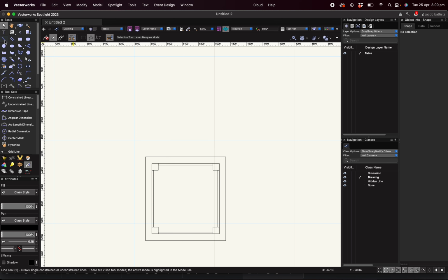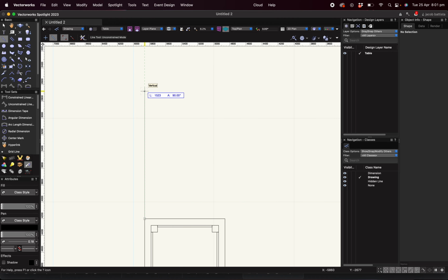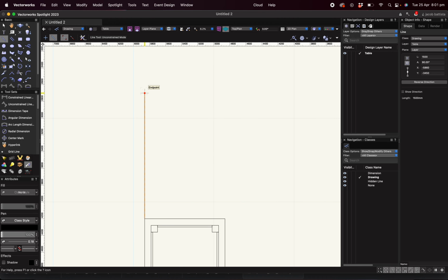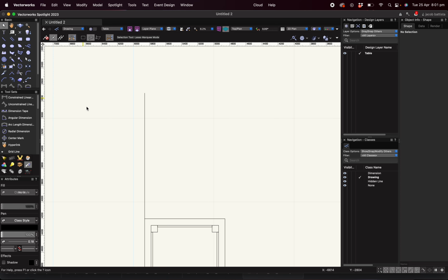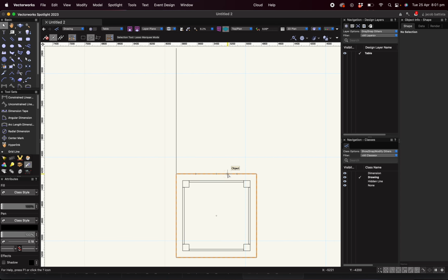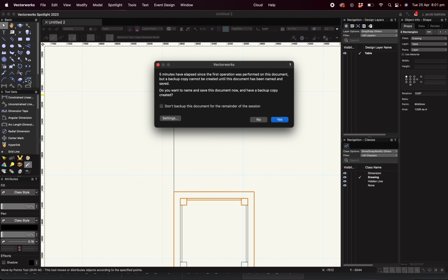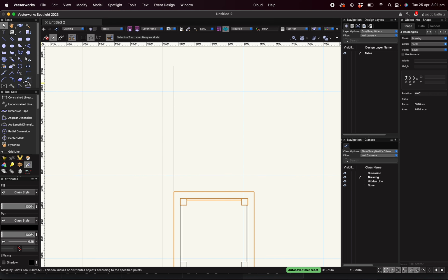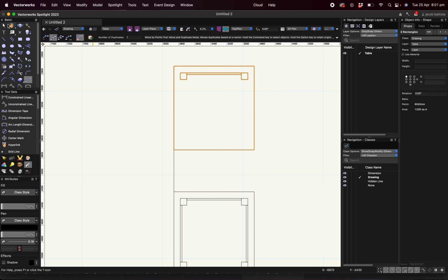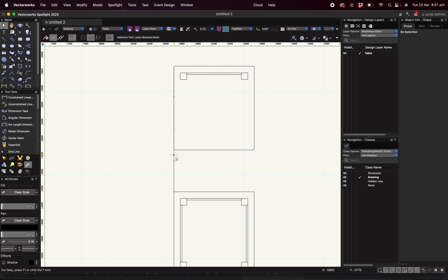So we can draw straight up. I'm going to draw a line here. Draw a line that's approximately 1.5 meters. I'm going to make it exactly 1.5 meters above this. And then I'm going to copy 4 things. I'm going to copy the table top and the 2 top legs and the top frame. And what I'm going to do there is use my object copy mode and just pull it straight up to there. This gives me all the information I need to set up my front elevation.